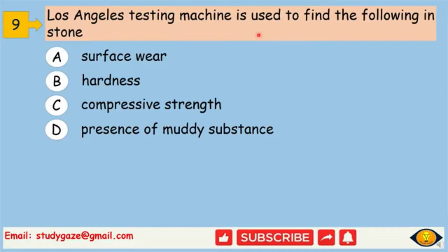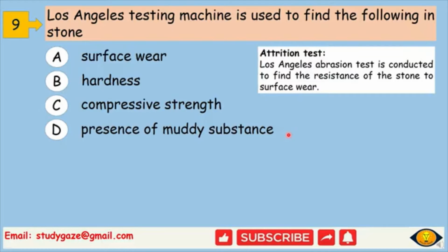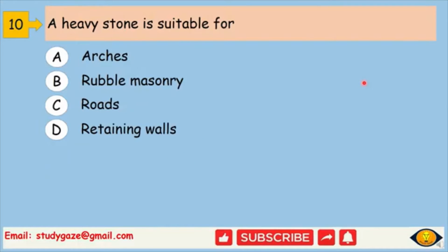9. Los Angeles testing machine is used to find the following in stone: surface wear, hardness, compressive strength, presence of muddy substance. The answer is A. Surface wear. The attrition test, the Los Angeles abrasion test, is conducted to find the resistance of the stone to surface wear. Number 10. The heavy stone is suitable for: arches, rubble masonry, roads, retaining wall. The answer is retaining walls.